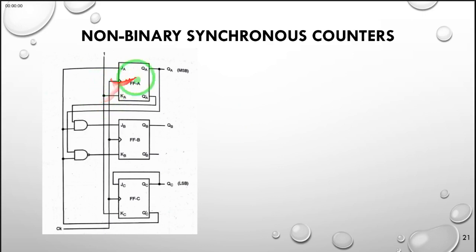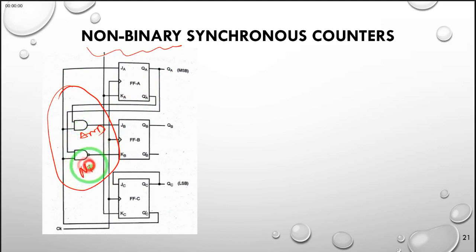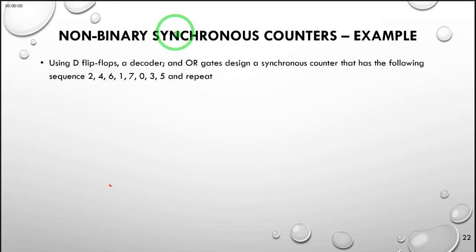You can see that after you have done the simplification, you have designed your non-binary counter that is able to mitigate the cases of lockout, and you find that our combinational logic circuit consists of only 2 gates, one AND gate and one NAND gate, and you end up with a circuit that implements your non-binary counter. So you may have another example that implements a non-binary counter. I'm not necessarily going to do it.